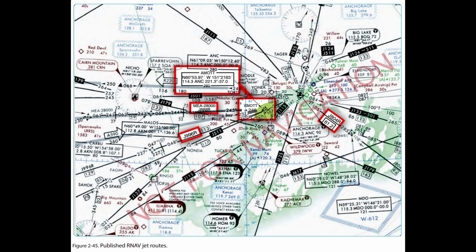Basic designators for ATS routes consist of a maximum of 5, and in no case to exceed 6, alpha/numeric characters in order to be usable by both ground and airborne automation systems. The designator indicates the type of the route, such as high/low altitude, specific airborne navigation equipment requirements, such as RNAV, and the aircraft type using the route primarily and exclusively. The basic route designator consists of 1 or 2 letters followed by a number from 1 to 999.